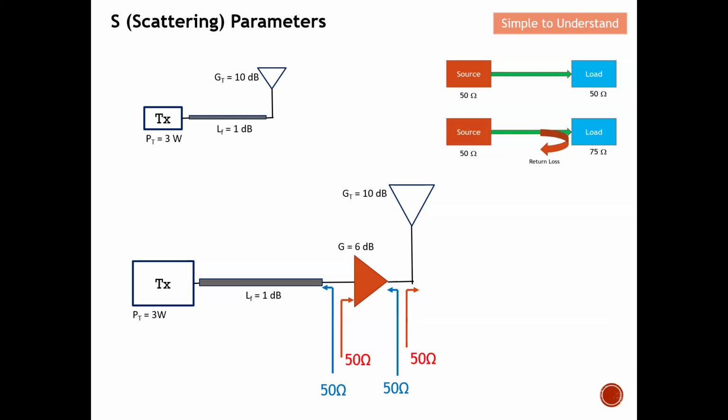So basically this is the rationale why we need to terminate one of the unused ports with 50 ohm before we commence the S parameter measurement. Again, I'll come to this, but this is the rationale.